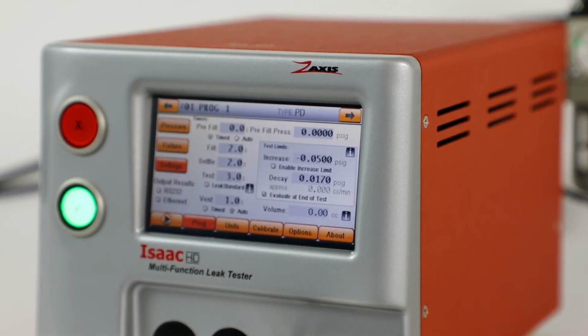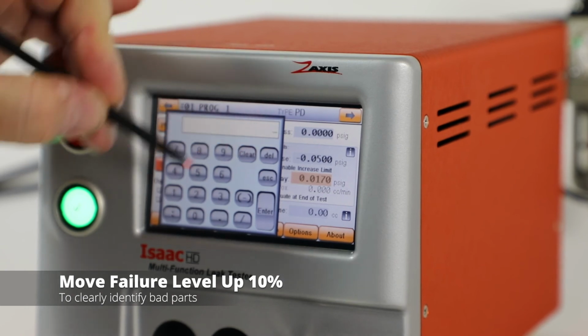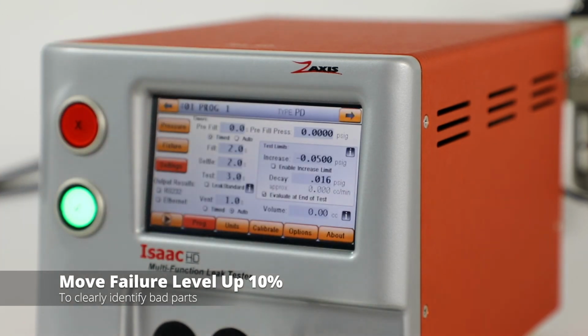But there will be some tests where you might get down to 0.0169. Now, is that value a real leak? It's so close to the leak, it's closer to a failing part than it is a passing part. So we will typically say, let's come off of that at least 10%. So if we take 10% of that number, we can now go to 0.016 as a good place to start. So now we're for sure going to catch everything that has this leak.